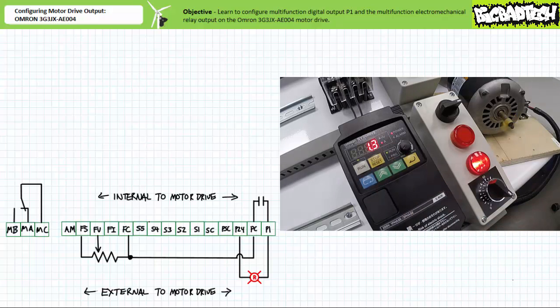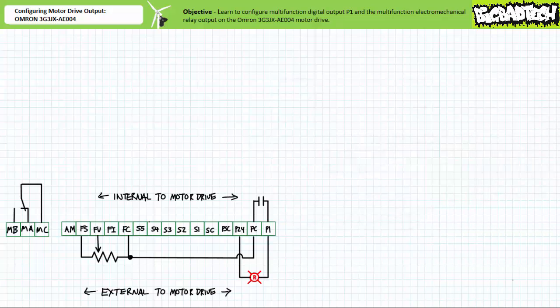When an operator presses stop, when current drops below 1.1 amps, the pilot lamp executing the overload warning function turns off. Obviously, an overload warning of 1.1 amps is way too low given this motor is unloaded. However, a technician can change the overload warning level and enable this function to get early notice of potential overload and take necessary action.